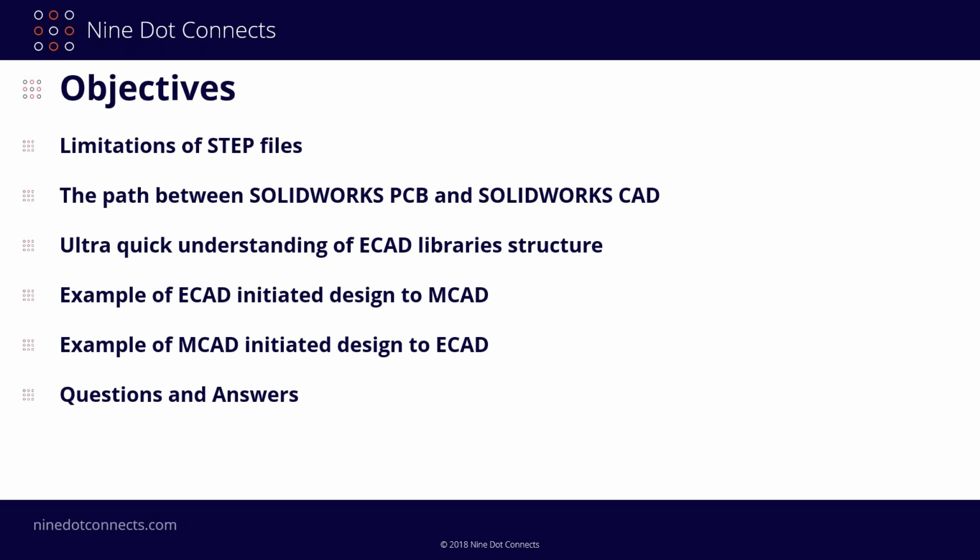An ultra quick understanding of ECAD library structures. The reason we want to do this is because it'll show you why the SolidWorks PCB to SolidWorks CAD connection seems a little bit convoluted, because we can't necessarily just push files from SolidWorks PCB into SolidWorks CAD and vice versa. We have to explain why things actually start on the ECAD side.